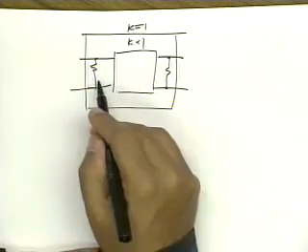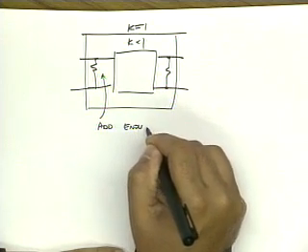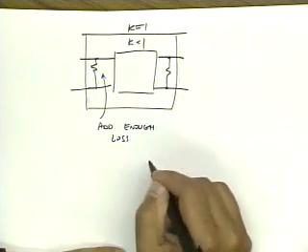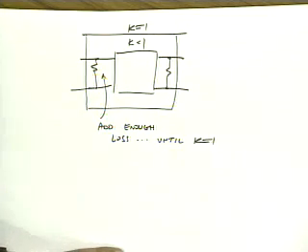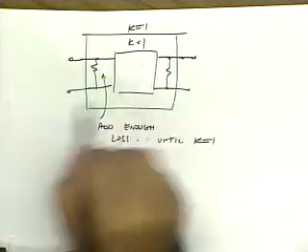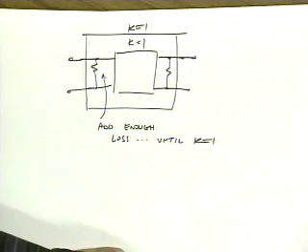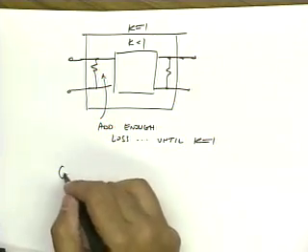So we add enough loss until K is equal to 1. And then we actually have something from the external two-port here that looks unconditionally stable. And so then the expression GT max applies.